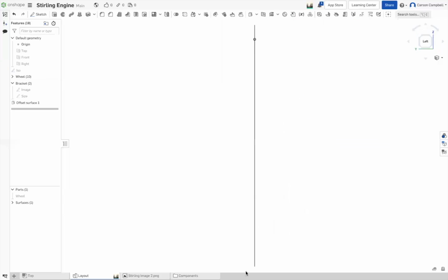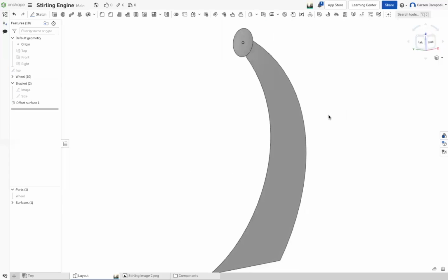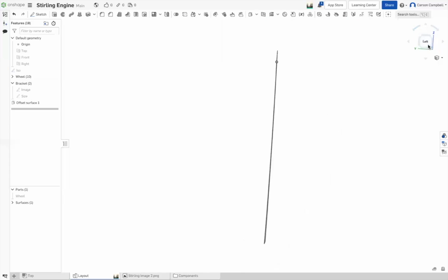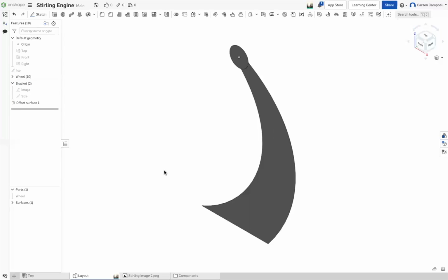So I'm trying to think of a fast way to do this. So you see at the bottom, I need an L coming off of that. Yep. Okay, I got the fastest way to do this in my mind. Sure, it'd be nice to be able to grab that edge and just drag it, huh? Yeah, direct modeling techniques will allow that. We could do that in a feature script and just come up with some handy tools to quickly create geometry. But that's later on. So let me show you how to create. Let's go to the ISO. So that's Shift-7. And the problem is turn your planes on.